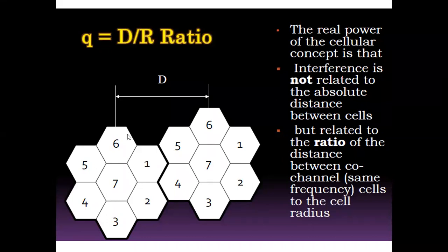The distance between them is shown, and we have to decide the minimum frequency reuse distance D in order to reduce our co-channel interference between the co-channel cells.